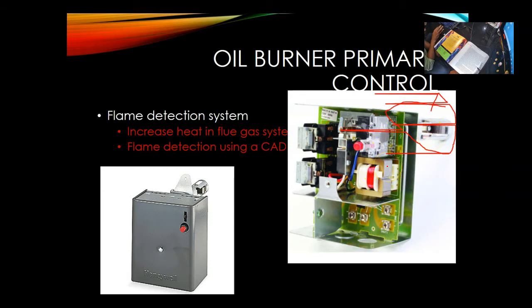We use them for systems that are grandfathered in, and we use them also for detecting temperature, but they are no longer up to code to be used to detect flame. However, if they're still there, you can keep using them. They work based on the heat that's coming out of the flue pipe.